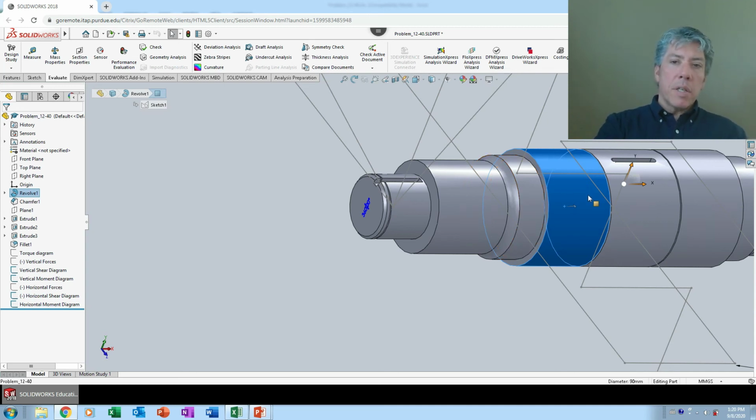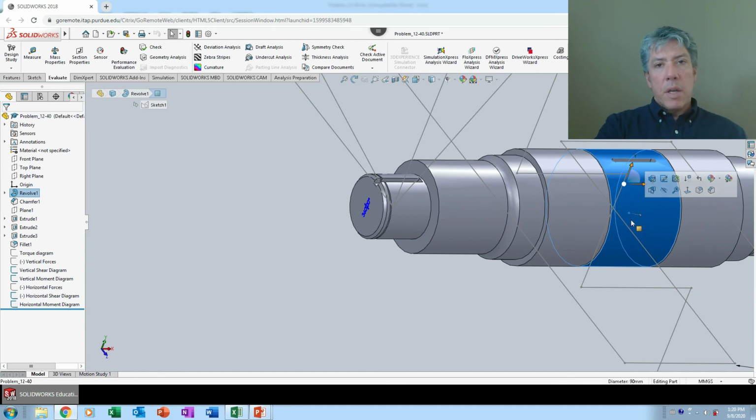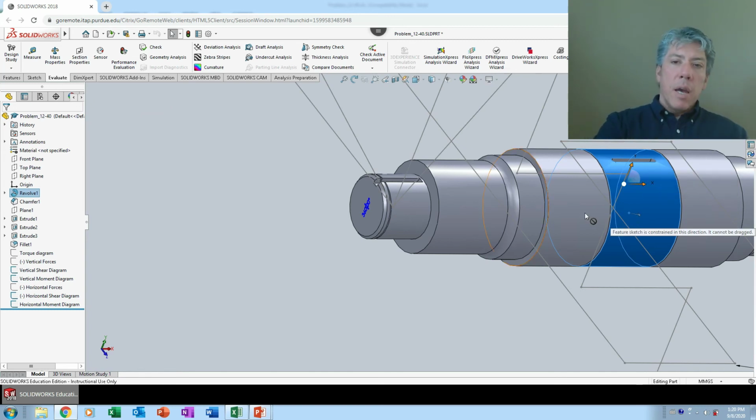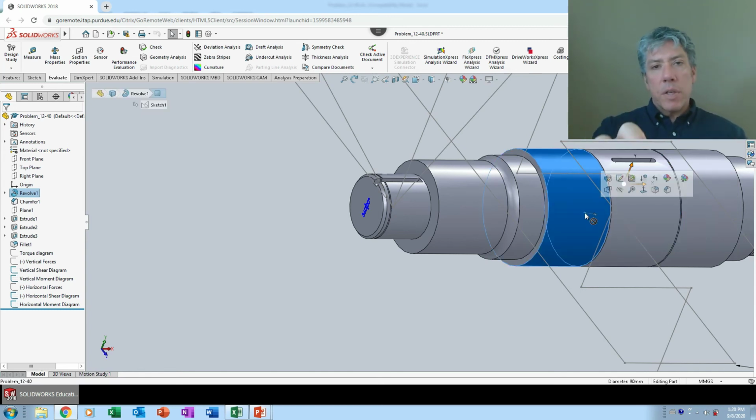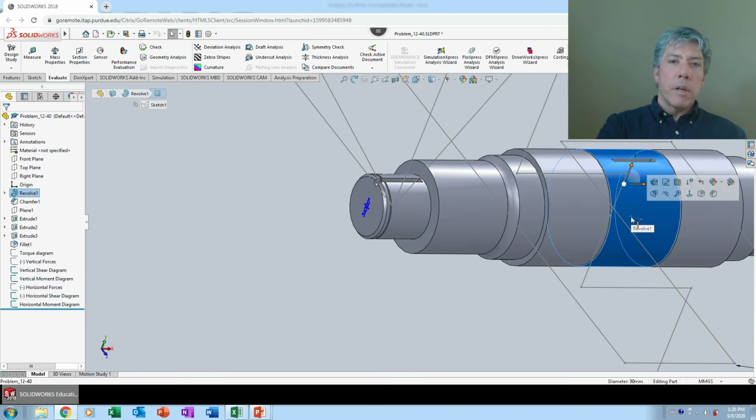Now, I do want this section smaller than this section because the gear needs to have a bore that matches this section nicely, so that when I put the key in and clamp it in place, hopefully it won't have any play on the shaft. That's the idea. But I don't want to have to pound it over this section, so giving it a millimeter of clearance is a fairly generous thing, so that then it can go on over here and be assembled easily.